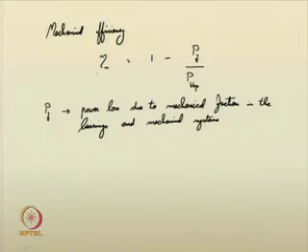So, that friction loss will cause the loss in power, means whatever power we were interested to transmit to the water, some of it gets reduced due to the connections of various mechanical equipments. So, that loss is now termed as mechanical loss, or the corresponding efficiency is termed as mechanical efficiency.